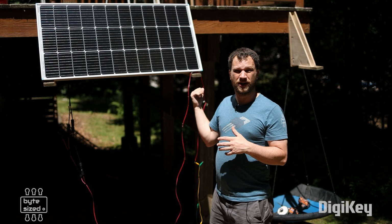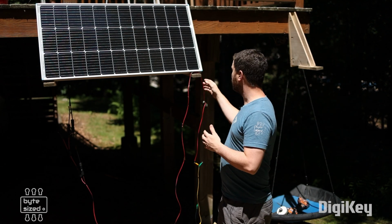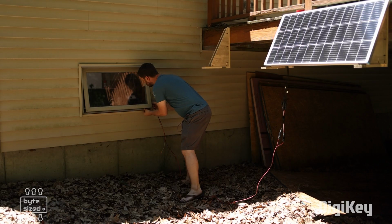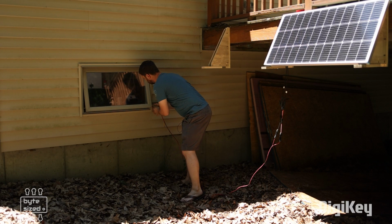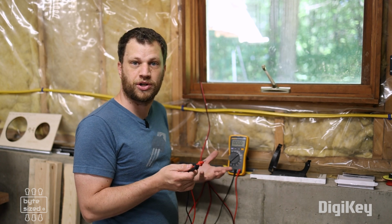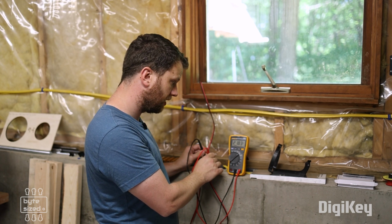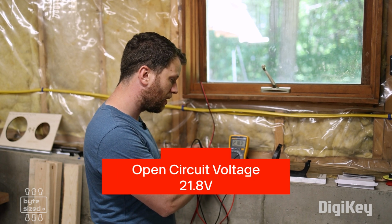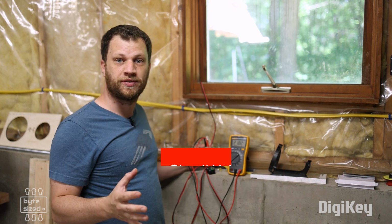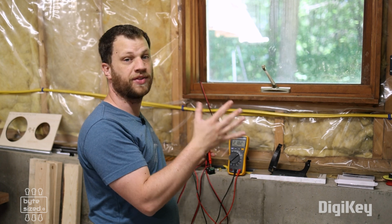I threw up some temporary mounts for the solar panel, and as much as I'd like to film out here in the sun, I actually attached a long enough cable and I'm going to feed it through my window so that I can work and film inside. The first thing I want to do is measure the open circuit voltage, or VOC, with no load attached to the solar panel. And to do that, I've got a multimeter here and I'm just going to measure across the positive and negative terminal. Okay, so in current conditions, my VOC, my open circuit voltage, is 21.8 volts. This is the open circuit voltage right now in time. This is constantly changing and it will change depending on the conditions outside.